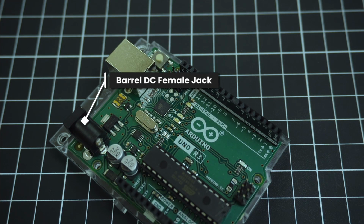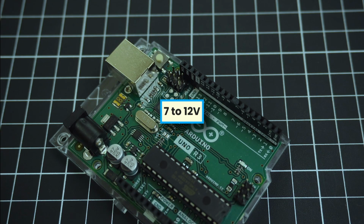Next to the USB port, you will find the DC power jack. This allows you to power the Arduino using an external power adapter, typically between 7 and 12 volts. This is especially useful when your project needs to operate independently without being connected to a computer.